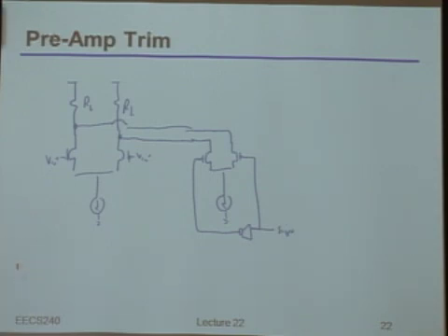In other words, once I know what the sign of the offset is, I will either turn on this transistor or that transistor, and that just decides which direction I'm applying the offset. As with before, that current source over there, let's call this I bias, and this will be I off. This will now be my current DAC.